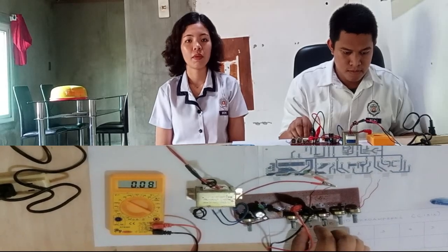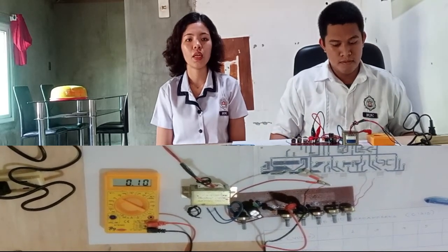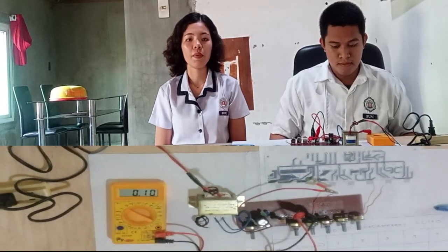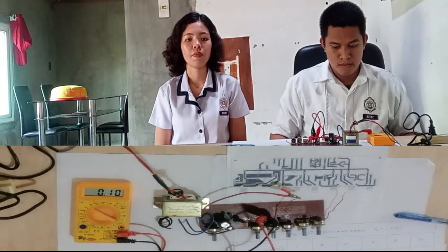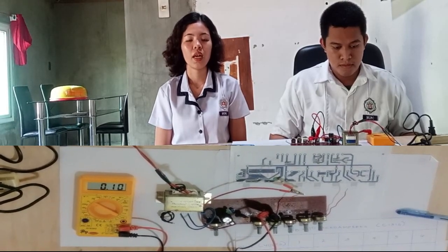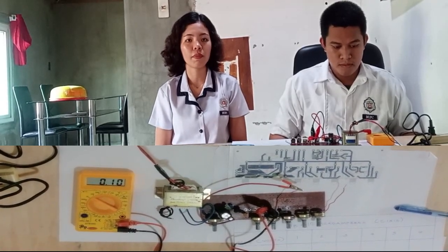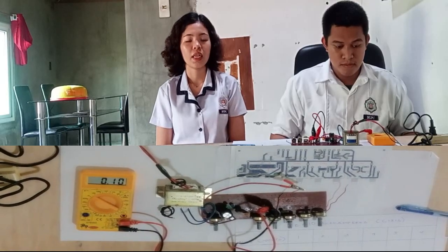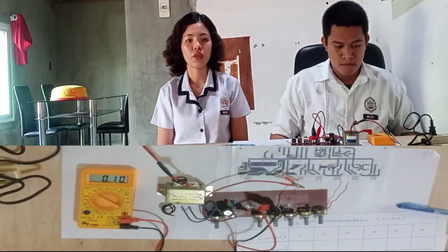At this time, the base current could have been measured with an ammeter, but that would require opening the current path and inserting the ammeter in series with R2 and the transistor base. Remember that anytime we add a resistance in series, the current decreases. Since we only have 10 microamperes of current flowing in the circuit, it is not a good idea to introduce unnecessary loading in the circuit.